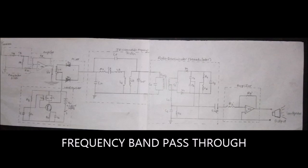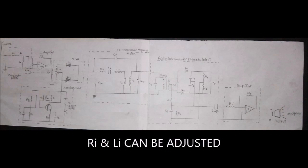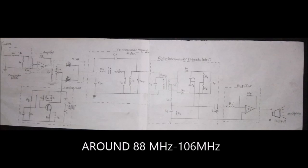In the first stage of the circuit, that is at the preselector filter, we basically allow the frequency band of the radio waves to pass through. For this purpose, a series RLC band pass filter is used. It can be shown that the allowed bandwidth is given by delta W_P equal to R1 upon L1, and hence R1 and L1 can be adjusted to allow the radio band of around 88 MHz to 106 MHz.